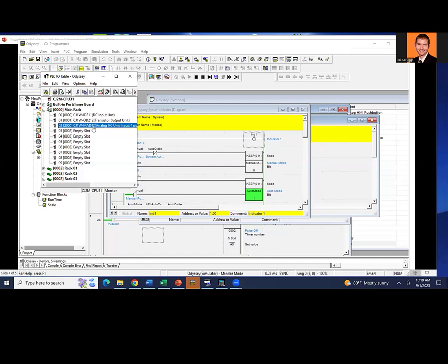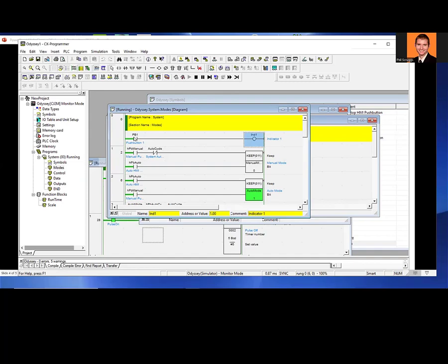Go look at your registers and turn your potentiometer, or whatever is on the trainer, and you'll see the number go up and down. I would have guessed, for instance, it says 2000, that the first address would have been 2000, and instead it ended up at 2005. So the only things I had to test on that unit were the 2 analog potentiometers and just see what the numbers did.